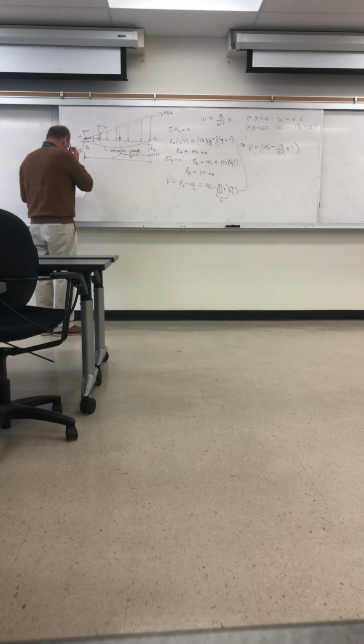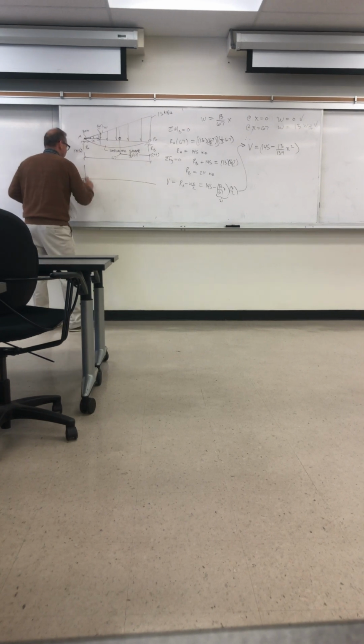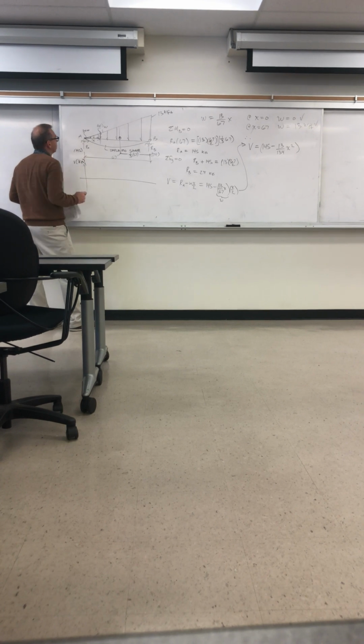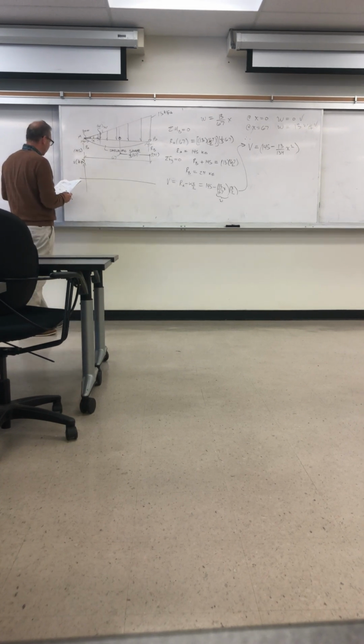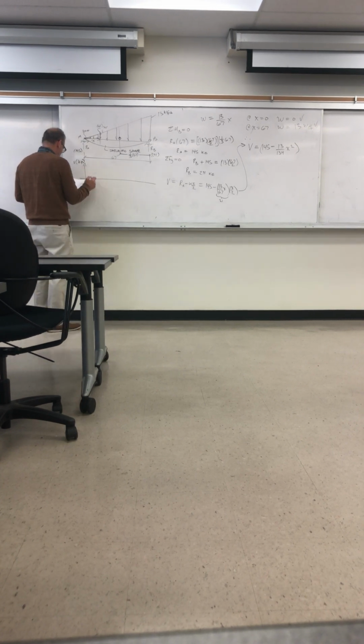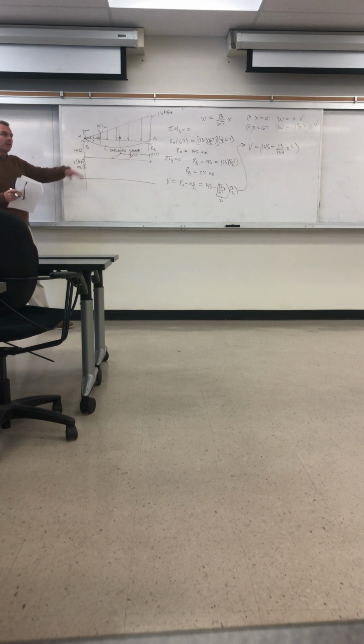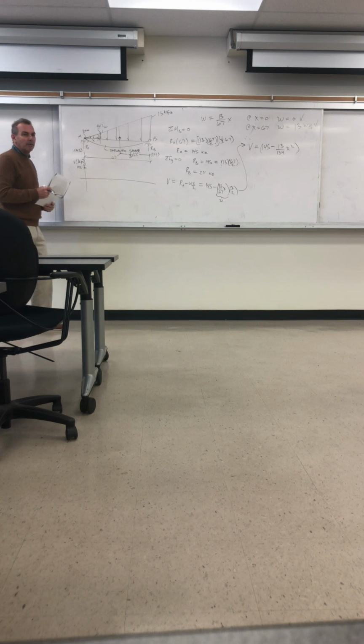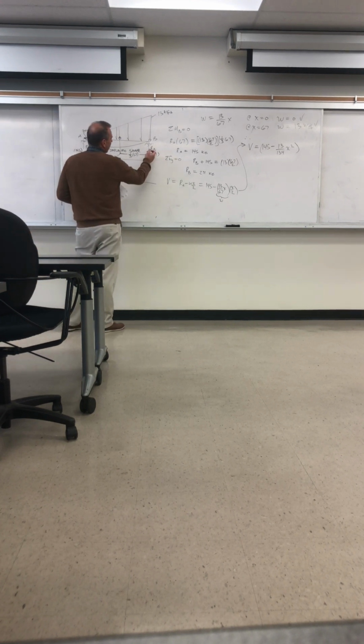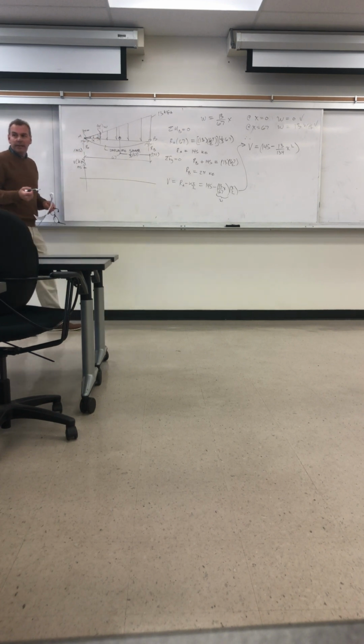So we can draw here the shear diagram. We know at the left it's 145 at that point. So whereas the moment is 0 at the left, there's a shear force, right? Just as we come into the beam, we've got shear force. And at the right, we know it's 291, but it's minus 291, right?